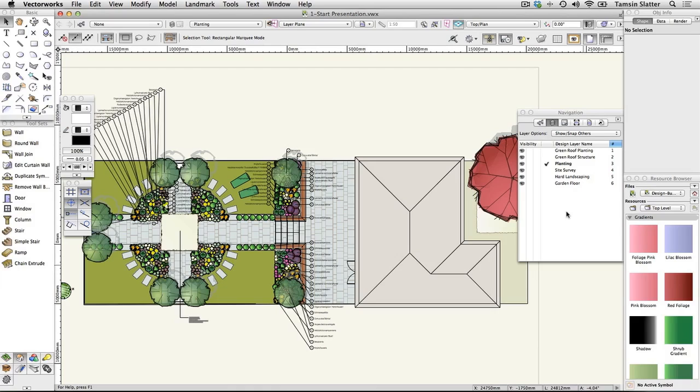Create sheet layers. Although we set the scale on the design layer and set the page size, I've mentioned several times that it really doesn't matter about page size on a design layer. Ultimately, on a sheet layer, you can present your model from any angle at any scale with as much information visible as you choose. A sheet layer is much more representative of a physical piece of paper than a design layer.